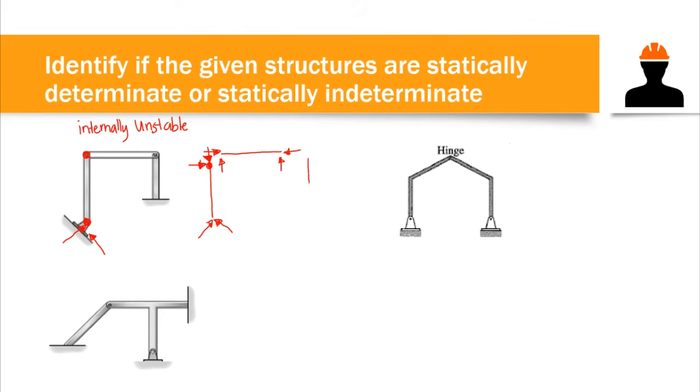And for the vertical leg on the right side of the structure, we have an internal hinge as well. We have downward and leftward forces. Again, our forces at that point are equal in magnitude but opposite in direction. Now on the lower end, we have a fixed support, so we have a vertical reaction, a horizontal reaction, and a moment reaction.